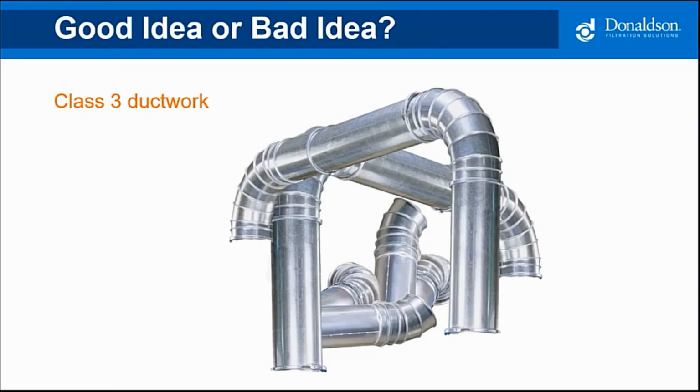Very good. All right. So when you're specifying for industrial duct systems, we want to make sure that you call out a heavy-duty industrial ductwork. Most dust collection applications use a class 2, 3, or 4 ductwork, which is designed to the SMACNA standards, okay? Typically, the higher the class rating of the ductwork, the heavier the gauge. So class 3 ductwork is considered a good idea for industrial ventilation.